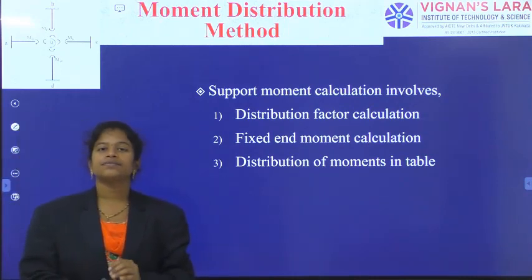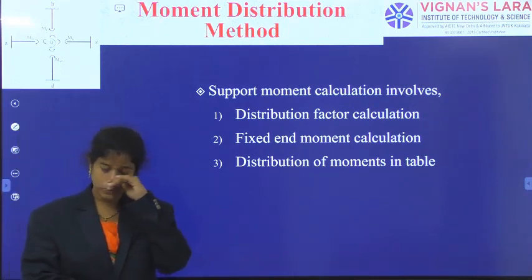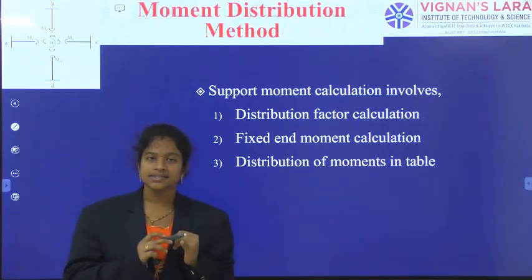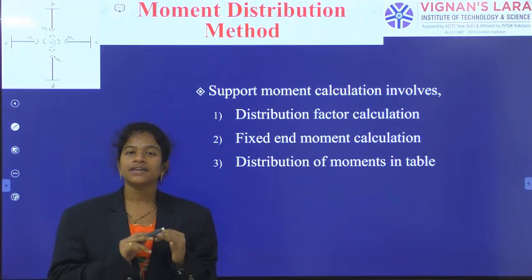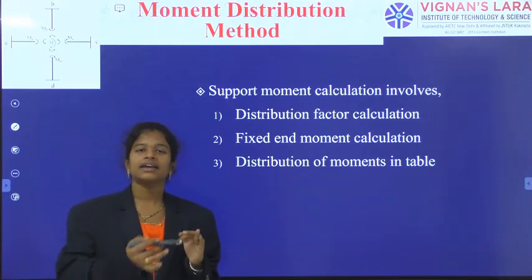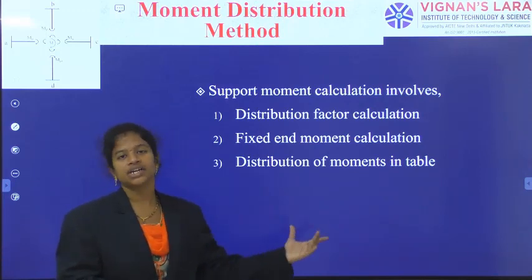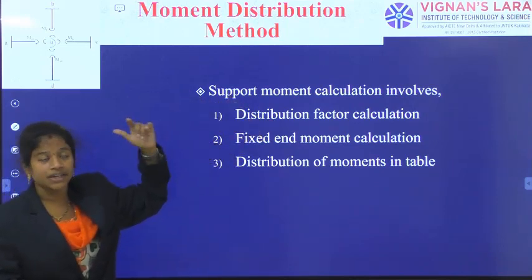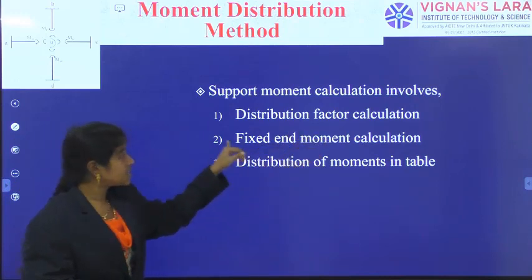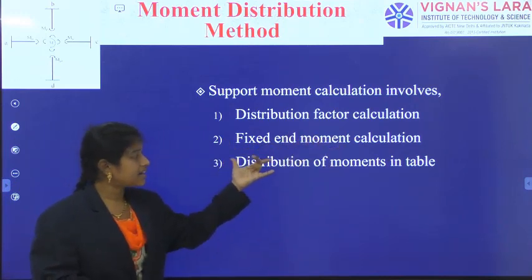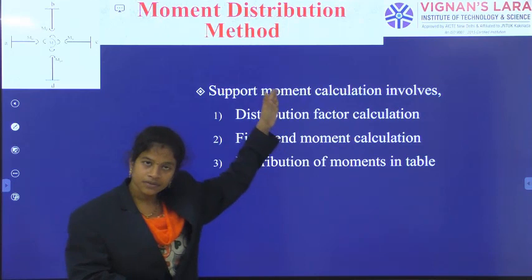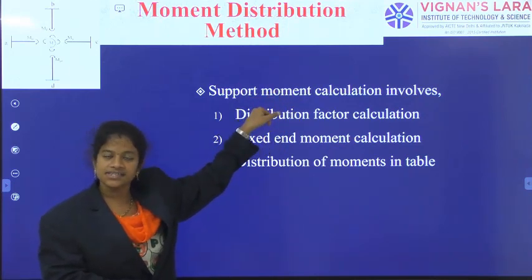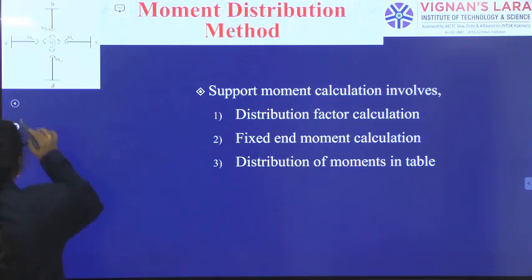The main thing is the calculation of support moments. The support moment calculation involves 3 main steps. Firstly, distribution factor calculation, then fixed end moment calculation, and then development of the moment distribution table. So these 3 steps combined will give the support moment answer. First step I am going on with is distribution factor calculation.